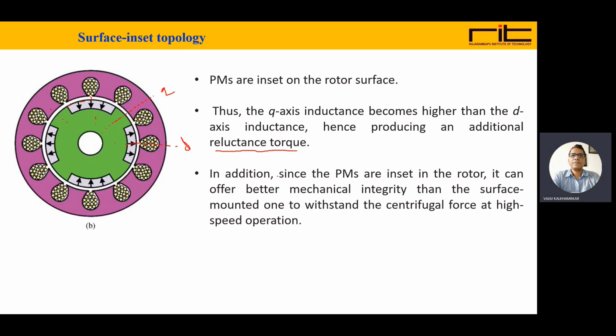In addition, the permanent magnets are inset into the rotor and it offers better mechanical integrity than the earlier type, that is surface mounted. It will withstand the centrifugal force at high speed operation, and there is no possibility of dislodging the magnets from the surface of the rotor.